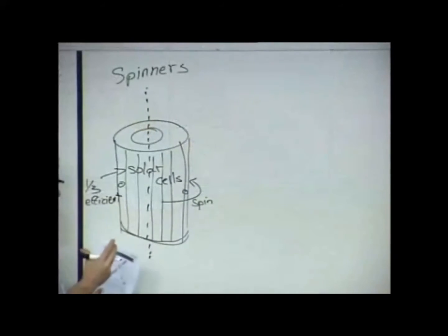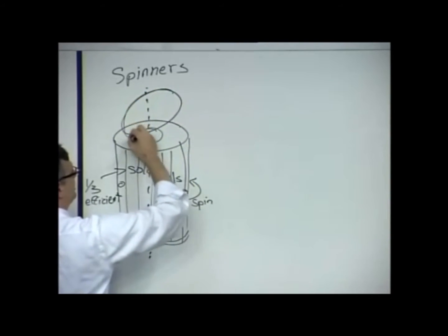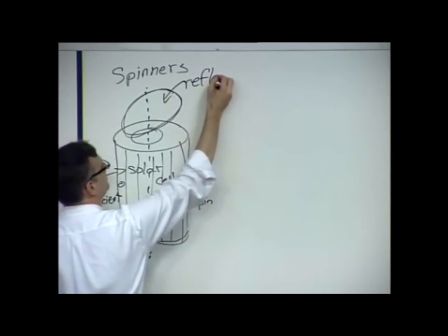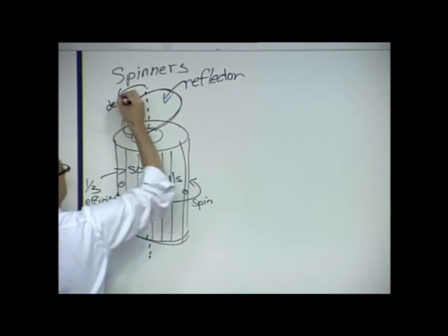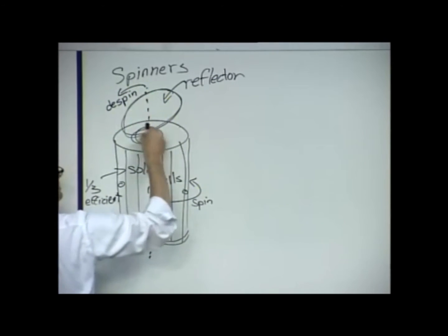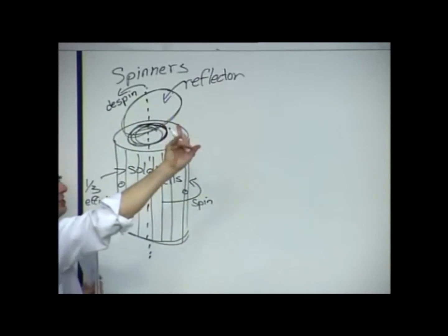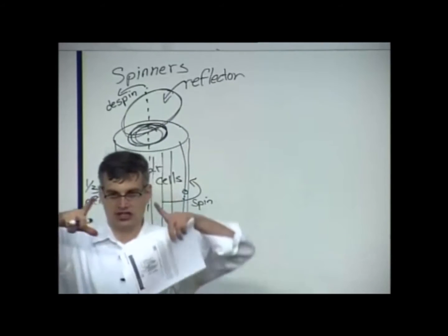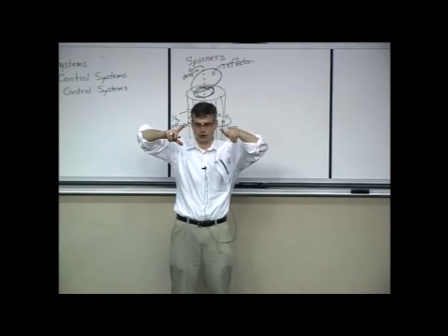you now have a platform that's moving. So how do you do communications? Well, a typical way is to take either the direct communications antenna or a reflector, often, and you de-spin it, meaning that this is now connected to a rotary mount, and you de-spin it at the same rate that you've spun the satellite, so that the reflector is always facing towards Earth.